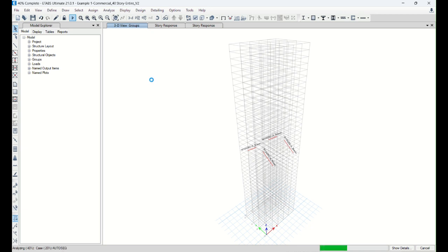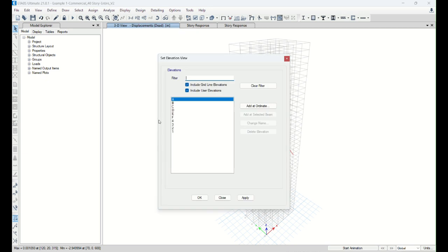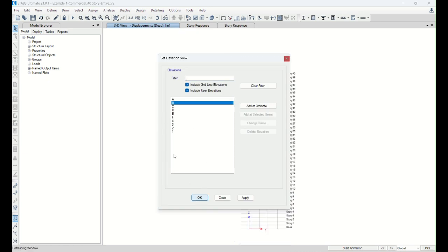So throughout all the load combinations, the dead load and superimposed dead load cases are going to be replaced with this construction sequence dead load. We try to avoid the situation where the bracing is holding up, so we avoid any kind of actual force loss in our column. So all right, so let me put this on and show the B line, B.